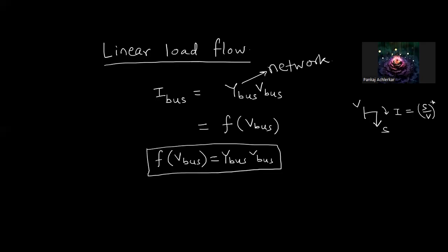That is fine. But most of the time, when it comes to real-time operation, the system size is very large and we need to perform a large number of load flow cases. For example, one application is state estimation, or we have seen the applications of time series load flow and probabilistic load flow. In those applications, we need to run the load flow several thousand times. For a large system, it will take time when we demand a very accurate solution.